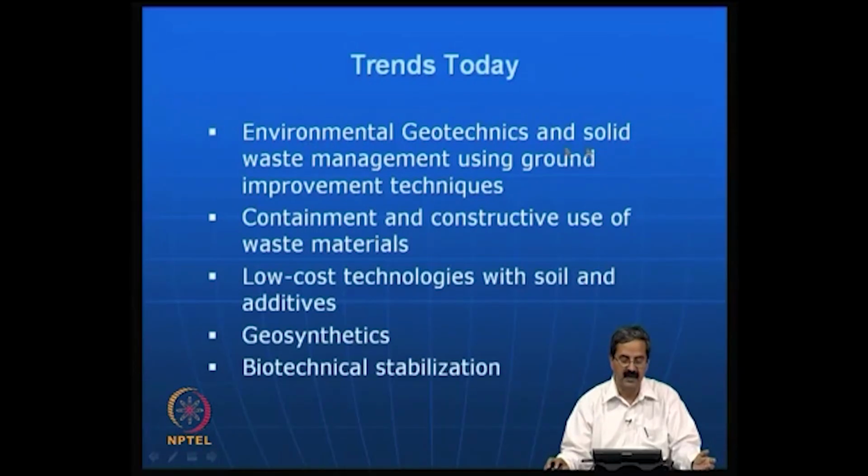Then there is solid waste management using ground improvement, in the sense that we are trying to use these ground improvement techniques to see that the landfill is not going to be harmful for us. The area in which the dump is there should not influence any of the nearby multi-storied apartments. Say for example, a multi-storied apartment is resting on a landfill. The first thing is that the whole area should be stabilized. How do you stabilize? You need to use some sort of ground improvement techniques. We will see that dynamic consolidation is a very standard method used. Dynamic consolidation, then stone columns, many of these techniques are used to stabilize waste dumps.